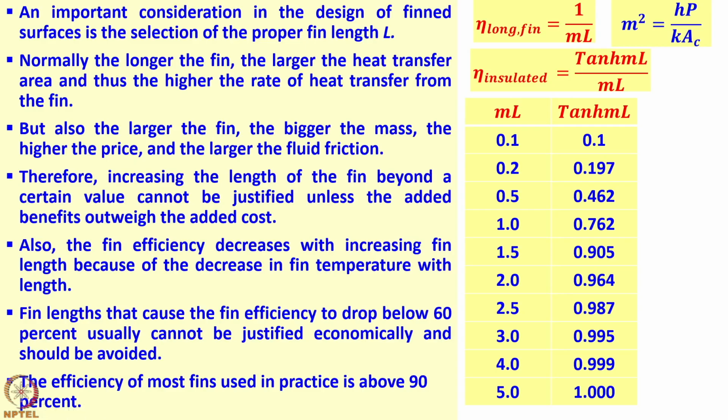Now, usually we would not like to go with a fin efficiency greater than 90%. So using these values, you can choose your ml such that your efficiency is of the order of 90%, depending on the fin tip condition you are using.